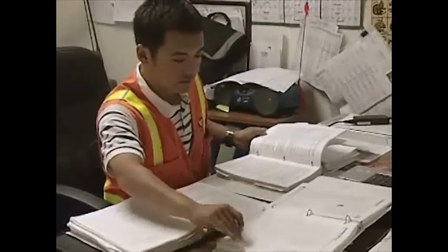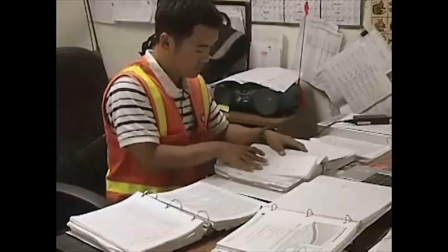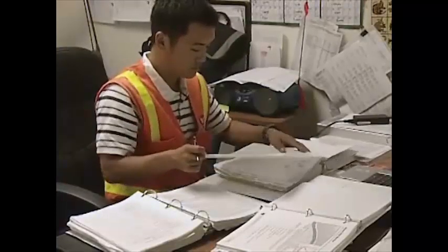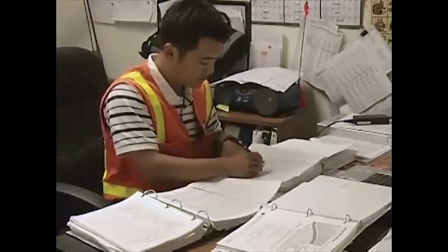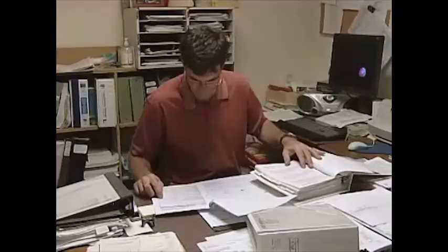This checklist must also be used for inspections unless the project special provisions require the contractor to use a different checklist. The contractor's Water Pollution Control Manager completes and signs the inspection form, keeps a copy in the on-site Stormwater Pollution Prevention Plan, and submits the original completed inspection checklist to the resident engineer within 24 hours. The resident engineer then reviews the contractor's operations for water pollution control compliance and files the inspection form in the Category 20 file at Caltrans.